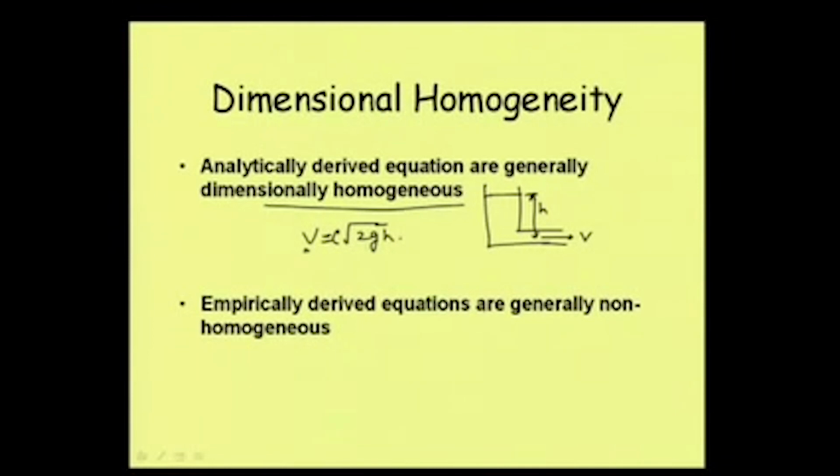So where is this coming from? We know that the head at this point is h, just on the upstream of this pipe. If we check the total head, it will be h. Z is the same along this line. We are talking about two points, this one is 1 and this one is 2. Now if we equate the energy head, at this point the head is equal to h, and there is no velocity just on the upstream, so the velocity head is 0 and only the depth head is coming. So h, and z is of course the same.